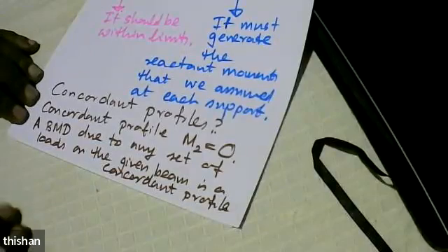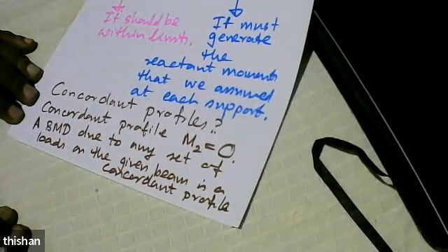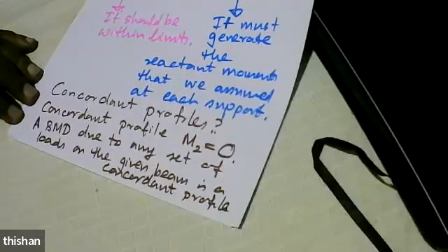So something has come to our rescue. It can be a point load, it can be a distributed load, it can be a load acting upward, it can be a load acting downwards. You do anything you like, any type of loading. Get a program like SAP 2000, model the beam, and then apply any type of loading, point loads, UDL, SAP will analyze it for you and will give you a bending moment diagram.